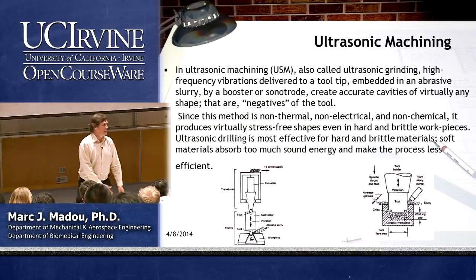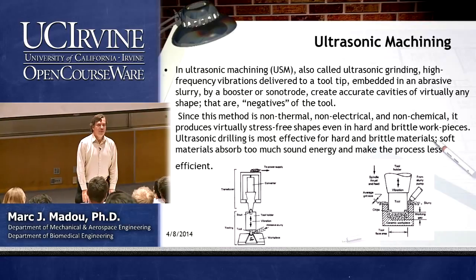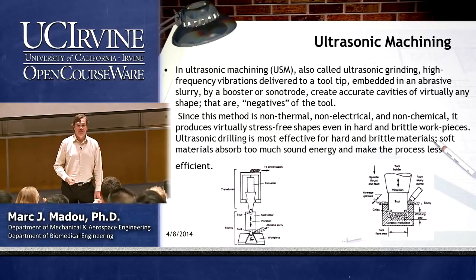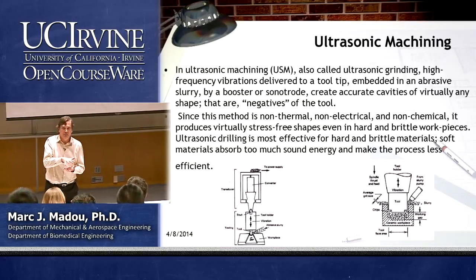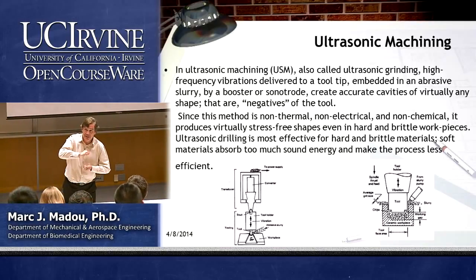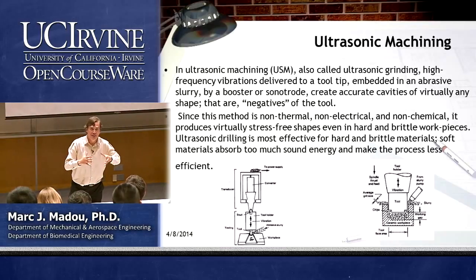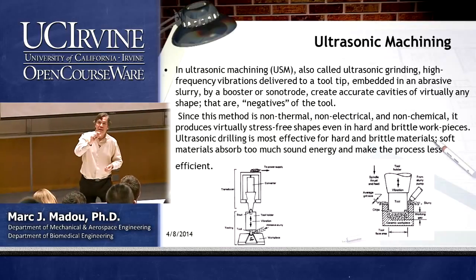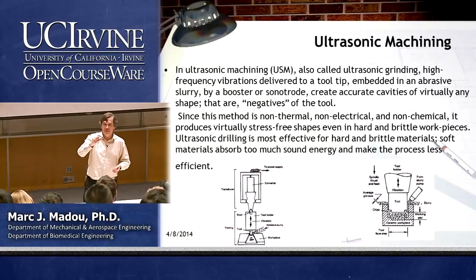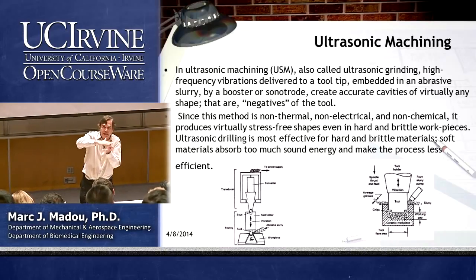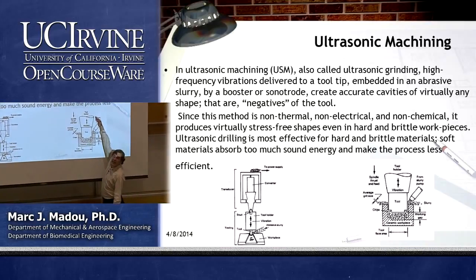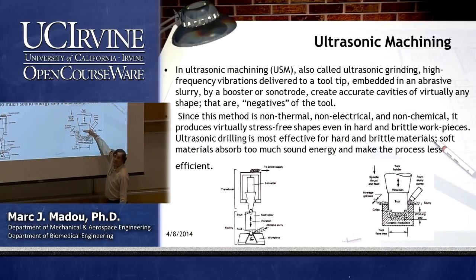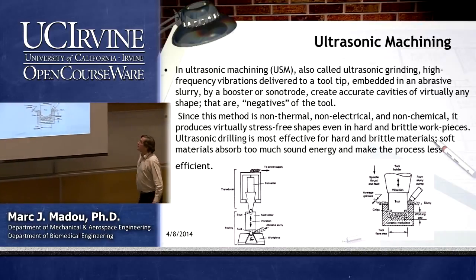So piezoelectricity, remember that? So piezo, from the Greek, pressure, right? So if you have certain crystals, let's say quartz, and you pressurize the quartz, you will have electricity. And vice versa, if you put an AC signal on a quartz crystal, the quartz will expand, contract. That's what happens. And so it's that expansion and contraction of the crystal stack up there that makes this go up and down. But so let's read through it together.